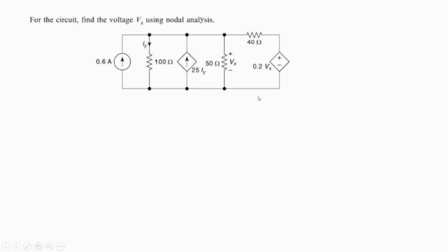analysis in doing so. So if we look at this circuit, here we see that there are several dots that are available here, but they are all one and the same node, because there are no elements connected in these wires. So therefore all of these are actually one and the same node, so I can call it node n1. This is n2, because between this point and this point there is an element that is connected, or we can say that at this node this element and this element are meeting. So therefore these two are the two nodes that are available right now.